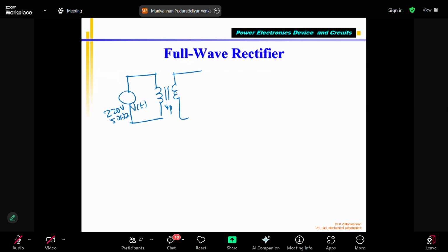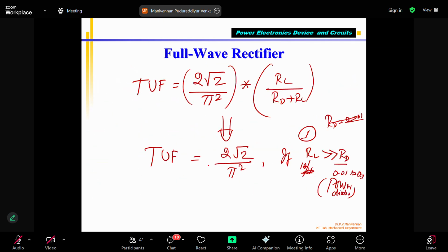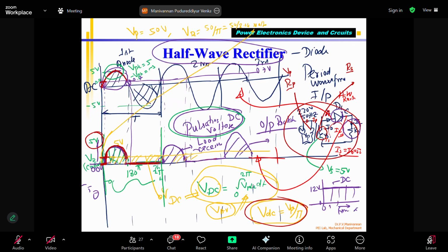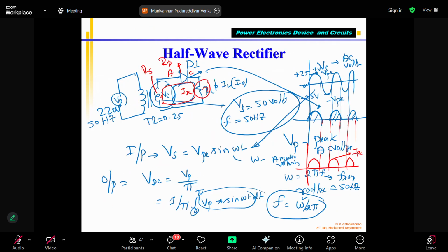And now this is the secondary. For this secondary, 3 wires will be coming. If you saw the previous half-wave rectifier, this is the input voltage, this is the primary coil, this is the secondary coil. You can see the secondary coil and primary coil each have 2 ends. I say end 1, end 2. For the secondary coil, this is end 1, this is end 2. So that means 2 wires will be coming out of the coil, where you supply the 220 volt input voltage, and the output VS is coming out of the secondary coil. It has only 2 wires.